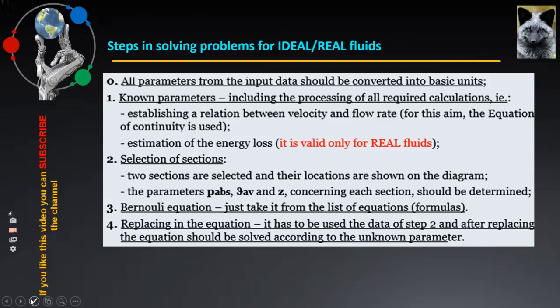Step 3 is just to copy and paste the equation of Bernoulli, in our case for real fluids. And step 4 is to use the data from step 2 and substitute it into the Bernoulli's equation. Finally, the equation is to be solved in terms of the unknown parameter.